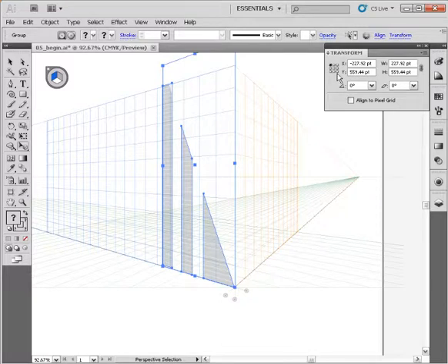Now, if you want to, you can simply click on that bottom reference point, or that bottom right corner, changing the reference point for these three objects. Therefore, we can line that up exactly with our origin here. Now, let's say for a minute you're doing sort of a technical drawing. Maybe you're building an object based on blueprints or schematics, and you need to know exact positions for objects. So this is actually going to be really helpful for precise placement of your objects in perspective.